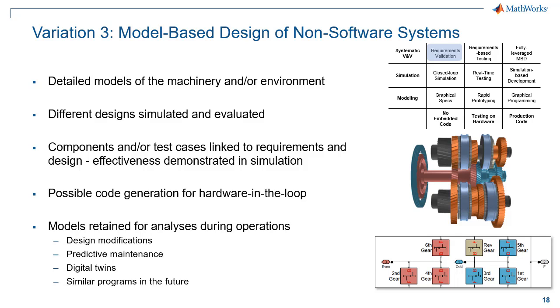It's a little bit expensive to run a launch vehicle experiment. And so what we would do instead of stressing our launch vehicles to the breaking point in the real world is we would run hardware in the loop sims, where we would trick that flight software into thinking that it was flying and stress it in a simulated environment to make sure it is satisfying its requirements. If you do all that, you should be confident in whatever you're building once you actually do implement it in the real world.